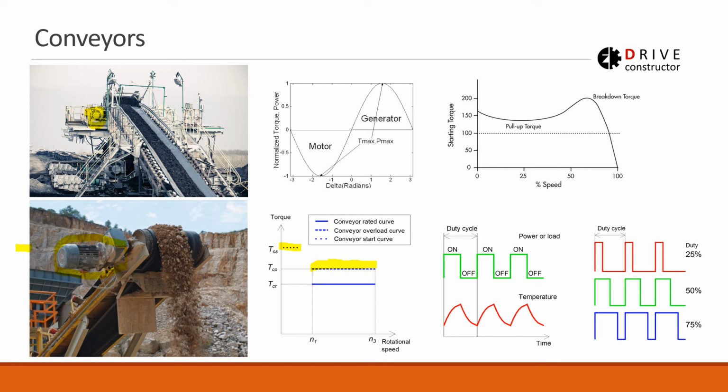And also we need to talk about duty cycles here. So duty cycle is a cycle when you have on-off operation. So for some time you have your motor and the rest of the system on because you suddenly need to move something, and then you're off, it is just resting. So what is happening to the temperature then in the motor? First of all, it is going up and down, up and down. It's important to make sure that it is not going up like that, and never stops, before the insulation burns. So it should be balanced thermally.